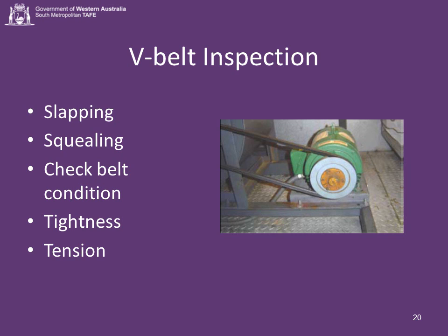Noise can be caused by the slapping of belts against the drive guard or other obstructions. Squealing of belts while running is usually caused by poor tension on the drive or by build-up of foreign material in the sheave grooves. It can also be caused by oil or grease between the belt and sheave groove. It's important to look at the tight side of a drive to be sure all the belts are running tight. If one or more belts are running loose, the drive needs to be retensioned. This could be caused by uneven wear of the grooves in the sheave.